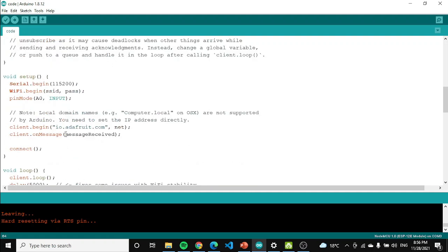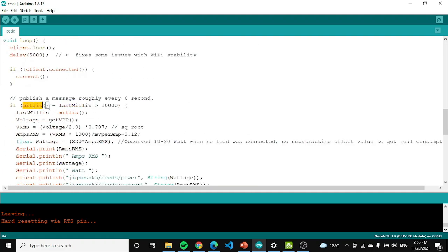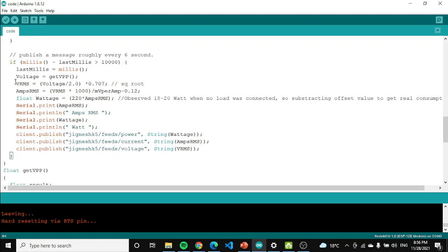Using these two variables, millis gives us the current time which has passed since the microcontroller was turned on. So we use these two to get the duration delay. We could use the delay method, but that would stop the execution of the other parts of the code. So the delay method is not a good choice here, and we have used millis and applied this method.